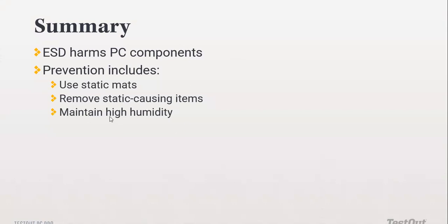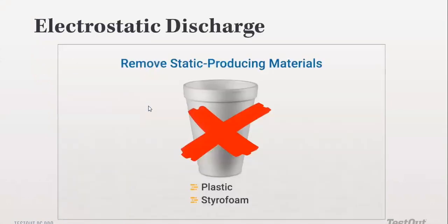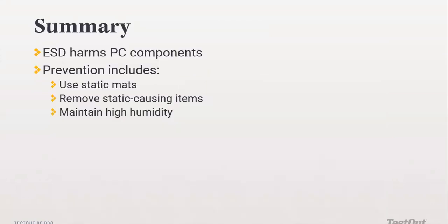We should also remove every static-causing item. We just talked about the styrofoam and plastic. There are components that can produce static electricity, so you should remove them from your working environment. And also maintain high humidity. Always maintain high humidity.